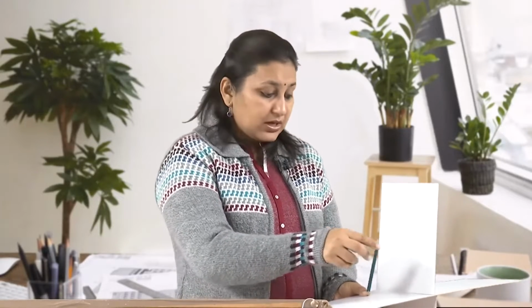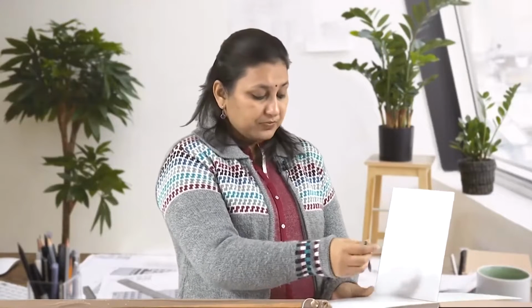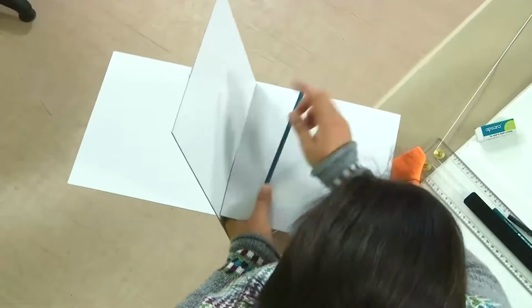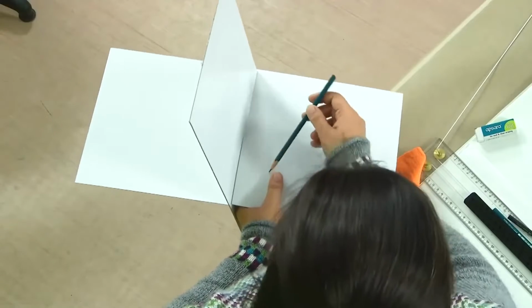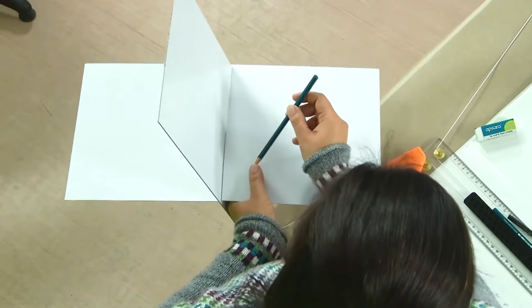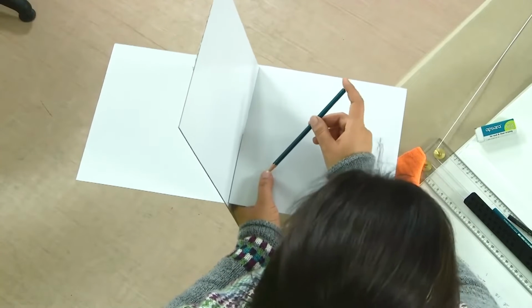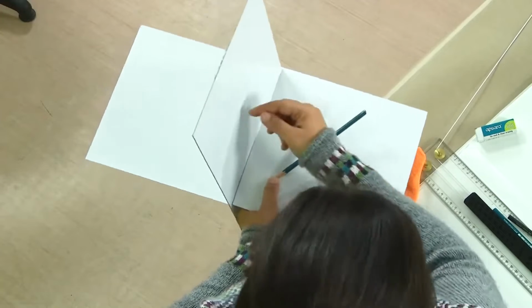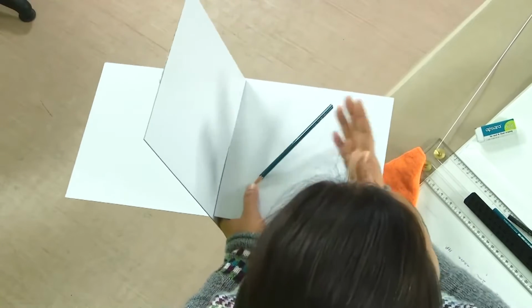As it moves such that the horizontal line, the locus of this point which is on top, remains the same, the lower one remains pivoted. In front elevation, we will see that the top point is moving in a straight line. The top point will continue to move in a straight line in such a manner that the line now makes an angle of, say, 30 degrees from VP.